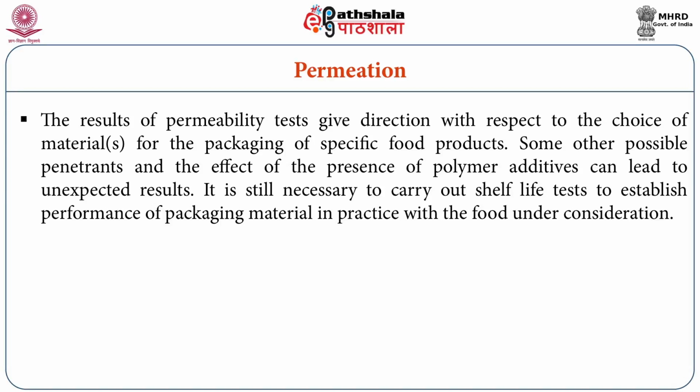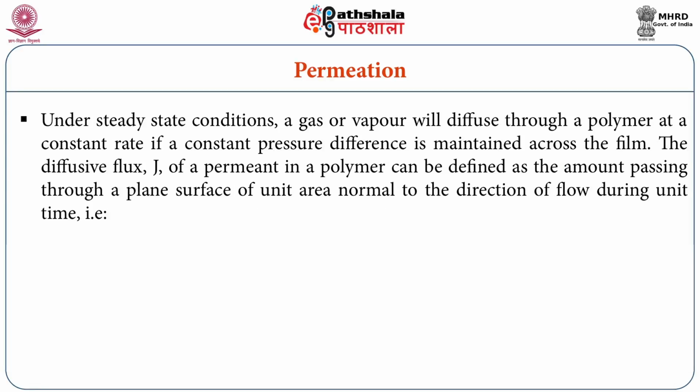The results of permeability tests give direction with respect to the choice of material for the packaging of specific food products. Some other possible penetrants and the effects of the presence of polymer additives can lead to unexpected results. It is still necessary to carry out shelf life tests to establish performance of packaging material in practice with the food under consideration. Under steady state conditions, a gas or vapor will diffuse through a polymer at a constant rate if a constant pressure difference is maintained across the film.